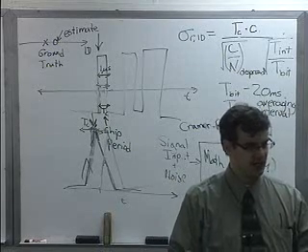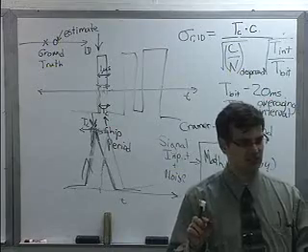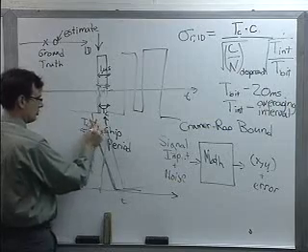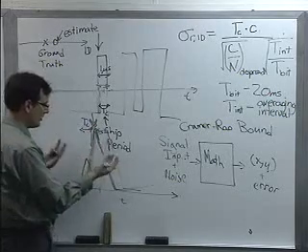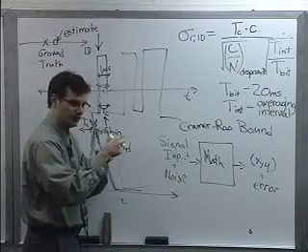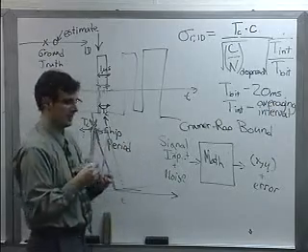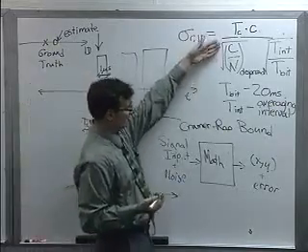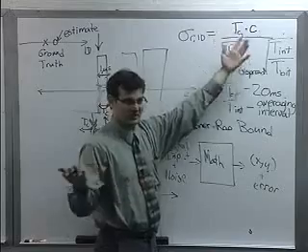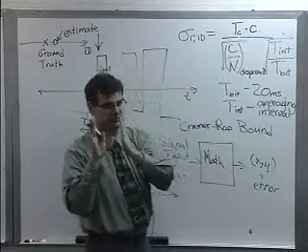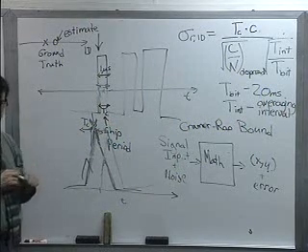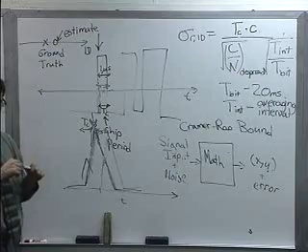And it's the same reason. As soon as you start degrading the signal, this assumption that you have a very precise, clean correlation peak breaks down, and you're pretty much left with just, oh man, did it show up in this bin, or this bin, or this bin? You can't pinpoint it much beyond that. And we see that in this formula, right? As the carrier to noise ratio gets really crummy, if you've got just as much carrier power as you do noise, then you're pretty much stuck with this bin level estimation of when precisely this signal actually arrived. Does that make sense? Did that answer your question?